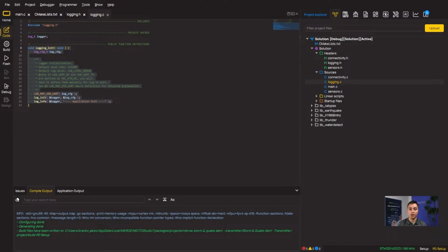And after that, I call the macro log map USB UART. And this maps the UART transmit and receive pins for the USB UART, using board header as the source of truth. It's fully portable across Microbus dev boards. Then I initialize the logger, log init, over here. Finally, I send a welcome message, log info, sorry. That tells me, or any user watching the UART terminal, that the system has booted and is ready.